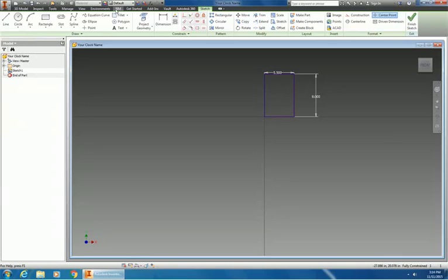Now we're going to use the next tool here. It's called a fillet tool, and you're going to select fillet. Now rather than 0.125, you're going to actually make this fillet 2.5, and you're going to select each of the top 2 corners. And what this does is this rounds out your clock on the top of it.